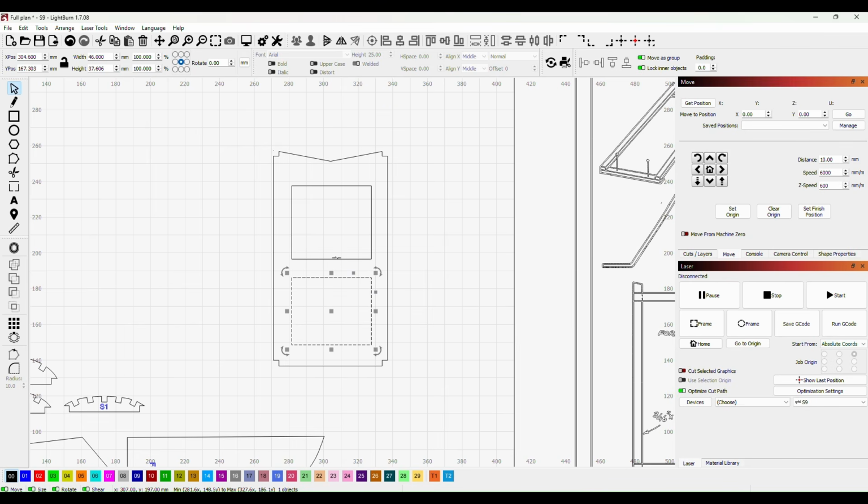I might just give us a bit more space there in the middle. There we go. So we've now got a space there where we can put platforms in. On the platforms we can put our battery and our controllers, etc., or receivers. So if I just mark that up, and we'll just make that 4mm, and we'll call that F1.